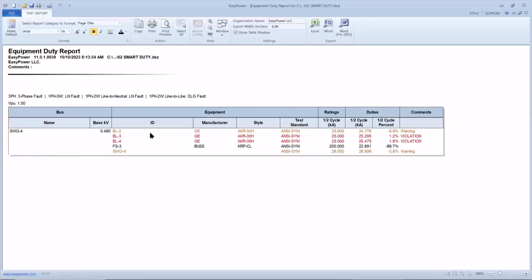And so this shows us for each of the devices, the fuse is not within its 10% bandwidth, but each of the breakers are, and in two cases we have clear violations and then two warnings. Mike's asking, can we actively auto-calculate as a default?